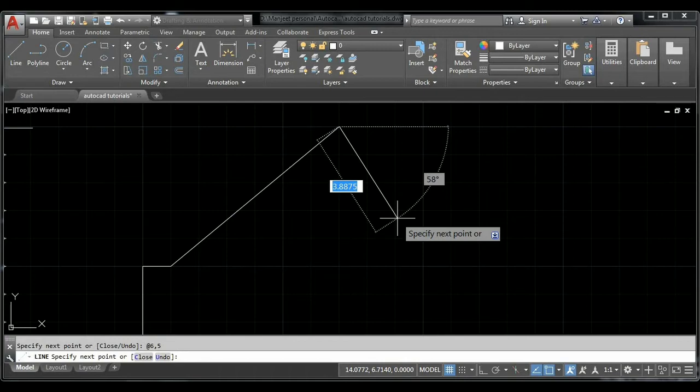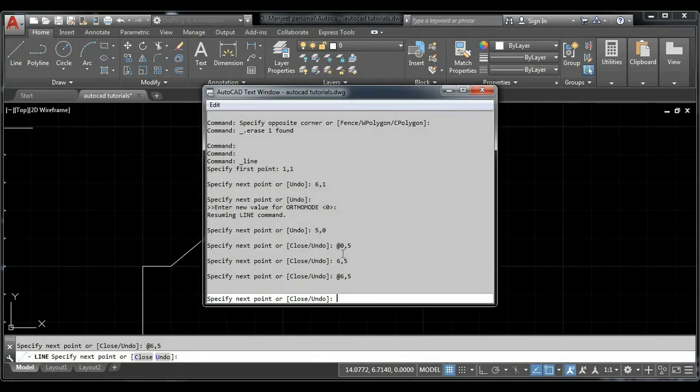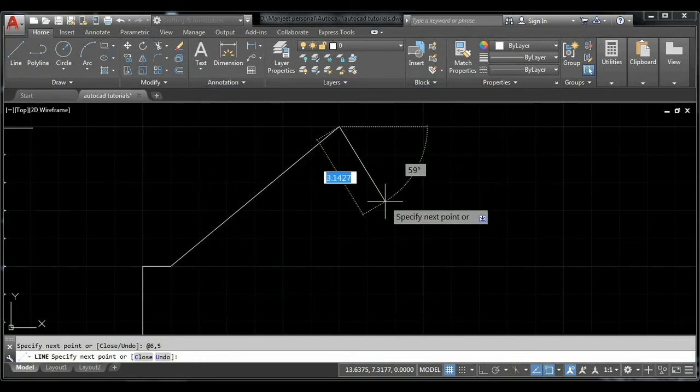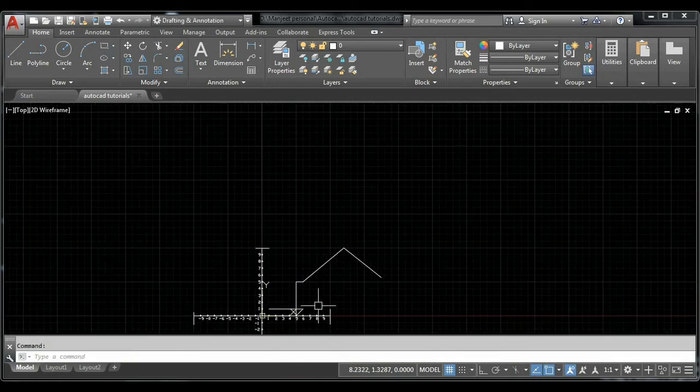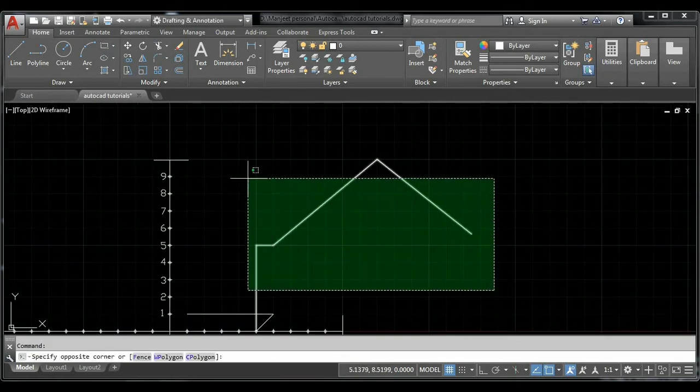And as you can see, I am pressing F2 key. When we were not specifying hash, it was going in relative rectangular coordinate system. This @ came by default because our dynamic input system was on. Therefore, I always prefer to keep this F12 off. Now I can make my line by directly specifying coordinates without using any kind of prefix.